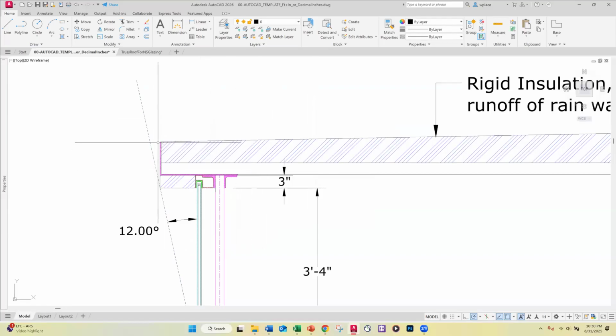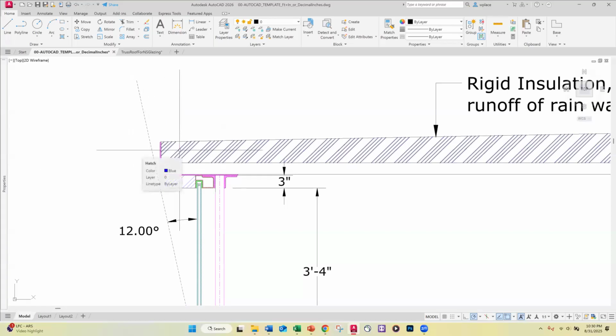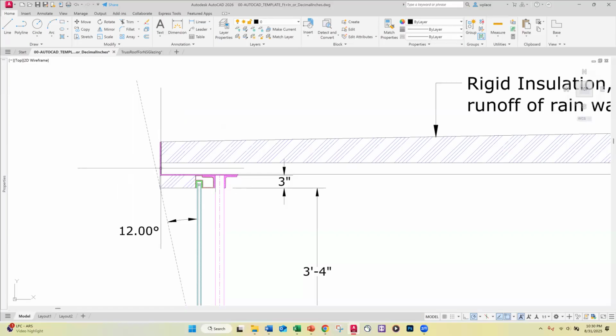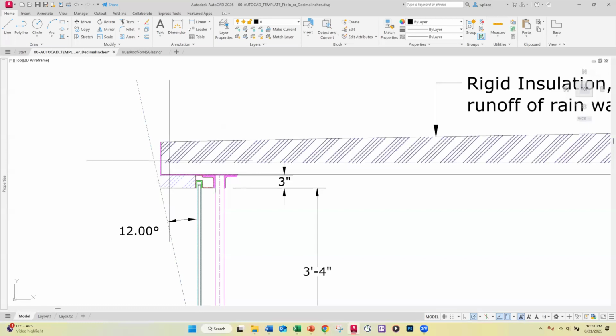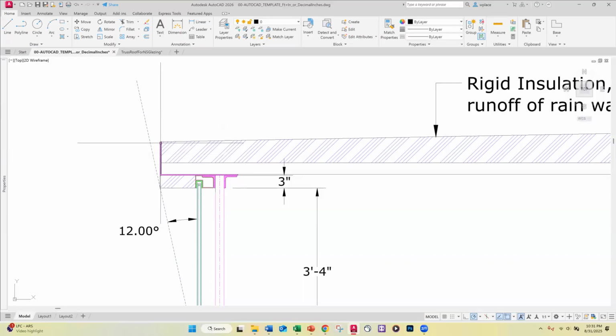This angle also comes up because on roof edges, people have this habit of laying a ladder against that edge. And so you can't have this so-called rigid insulation. It's more rigid than soft insulation, but it's not very rugged. And if people bash the edge of it with a ladder, it's going to damage it. So we have this angle here that comes up and seals off the end of our 3-inch corrugated decking. In this case, we have 5 inches of rigid insulation.